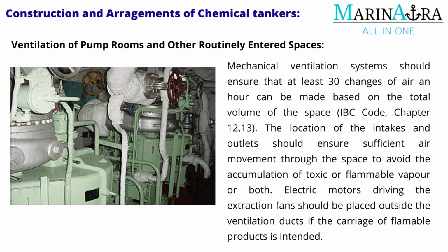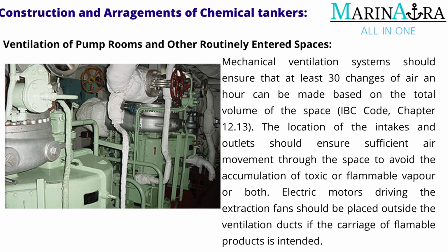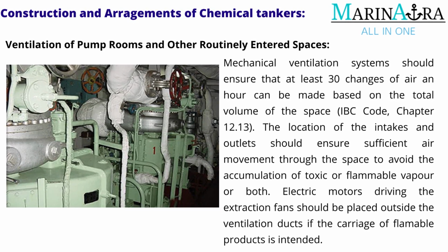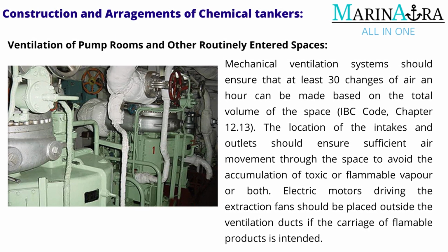Ventilation of pump rooms and other routinely entered spaces. Mechanical ventilation systems should ensure that at least 30 changes of air an hour can be made based on the total volume of the space. IBC Code, Chapter 12.13. The location of the intakes and outlets should ensure sufficient air movement through the space to avoid the accumulation of toxic or flammable vapor or both.